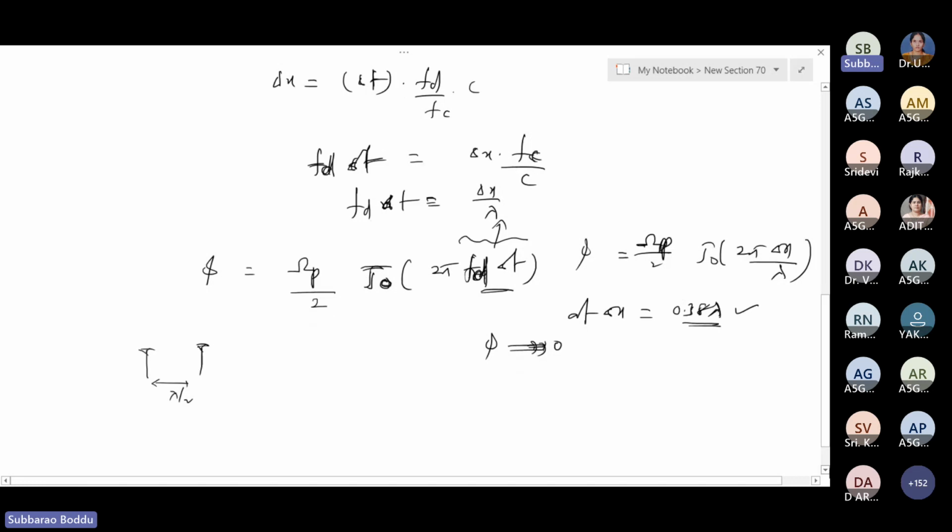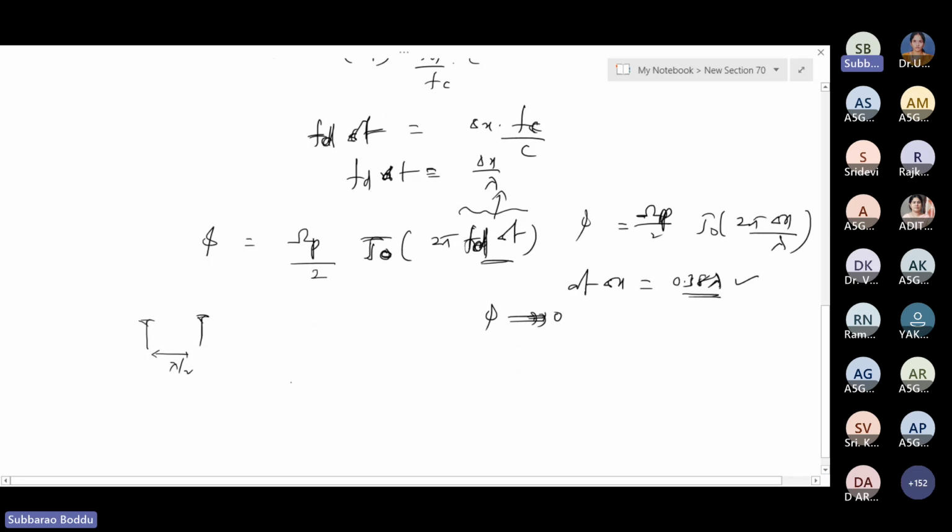We should also note that when you talk about wireless channels, the angular spread defines, in the space domain, the richness of the scattering or the poorness of the scattering. Here the rich scattering results in the parameter I am defining, the coherence distance. As I mentioned, when you say the channel variability in time, we said the